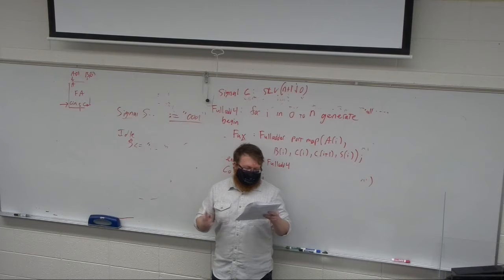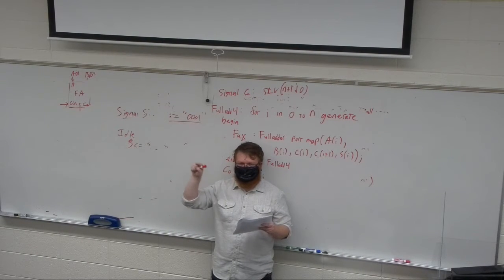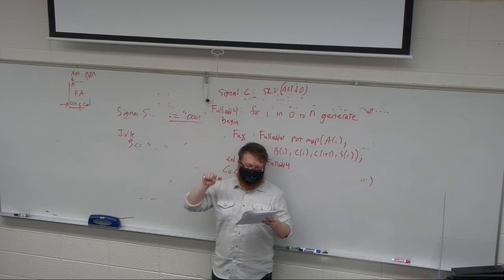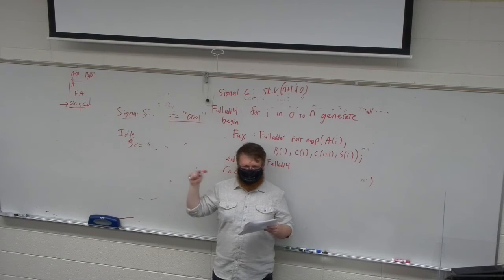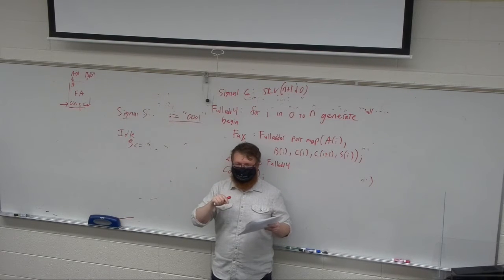The SPI master errors: when I initialized it, I said it has the range of 0 to 15, but then I later wrote bit count is equal to 16, and that doesn't throw an error anywhere. Initially, it doesn't have any squiggly lines, but it will cause an issue once you run the simulation, saying out of bounds.